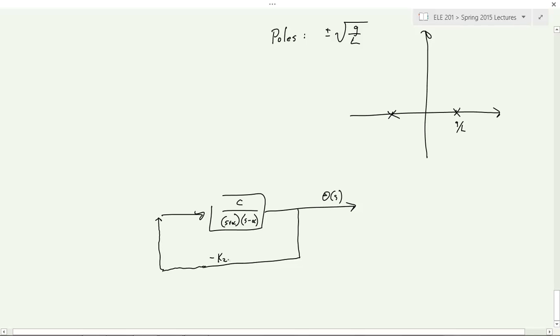But it's oscillating a lot. Now, if we work out where the location of the poles and the zeros are, well, it's oscillating. We have this type of feedback. We'll see, and you can work this out because we don't have time here. The 2 poles, one was positive, one was negative. As you apply proportional feedback, the poles move together towards the imaginary axis. If you keep applying enough feedback, which we have, they move up the imaginary axis.